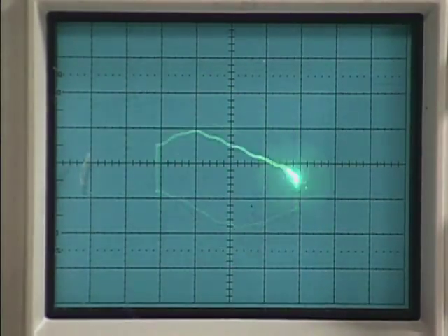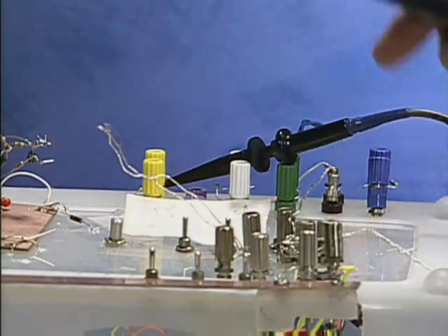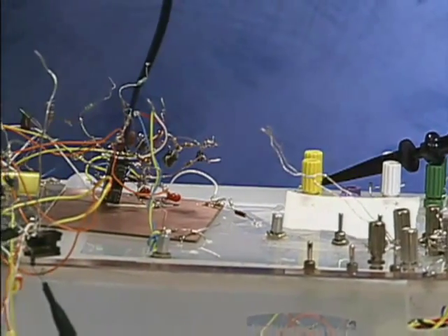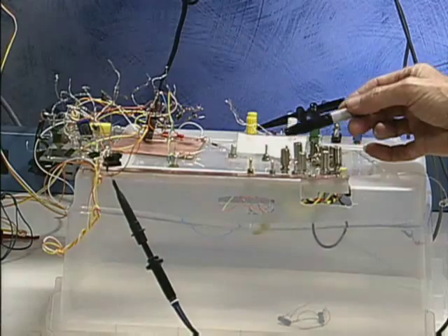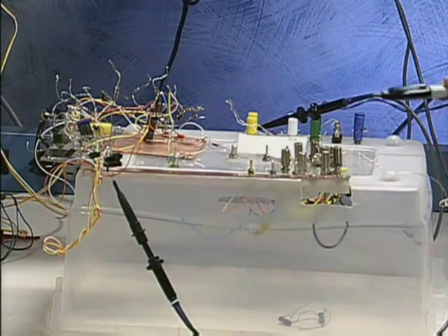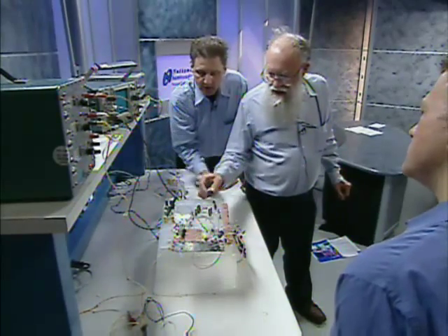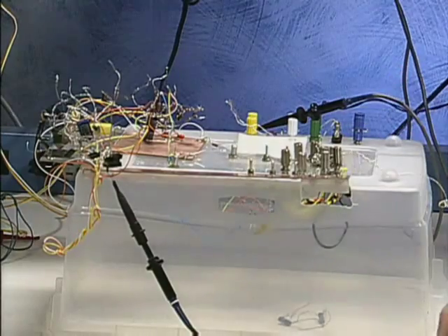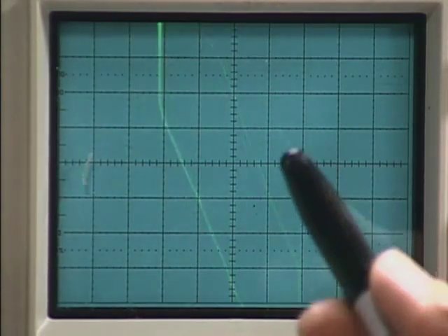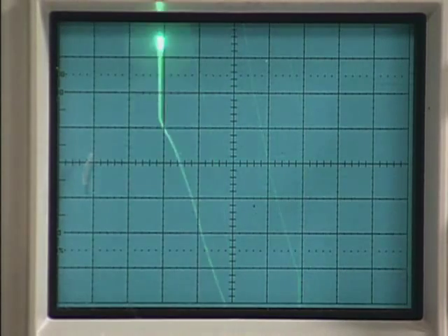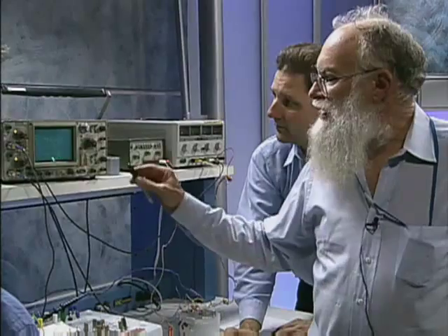So here we have the current coming in on 2 wires into this signal, where we have a separate power supply at plus minus 12 volts to distinguish the difference between this voltage and this voltage. And this chunk of wire is what you're measuring, a tiny little chunk of copper wire, 1 milliohm actually, and measuring that at the part per million level. And watch it cool off. As it cools off, it's got very small error. As the bridge balances, it would go straight. If the bridge is balanced, it will go straight.